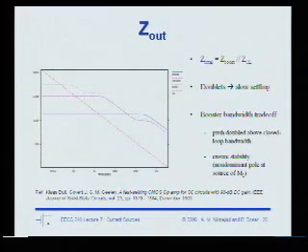Once you go above 10 Hertz, there's no gain, so you would expect that the impedance should approach the impedance of the cascode device, right? And in fact, you see that it's coming very close to the impedance of the cascode, and eventually it just looks just like the impedance of the cascode, right? Has no effect. Okay.